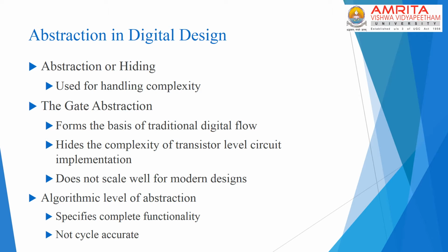Abstraction or hiding is a very powerful tool that has been used by both the hardware and software community for a very long time for handling complex systems. We are all familiar with the gate abstraction, which is commonly used in designing gate level digital circuits. This was the basis for the traditional design flow using the TTL ICs. Now, in this level of abstraction, the lower level details and the complexities of transistor level circuit implementations are more or less hidden from the digital designer.